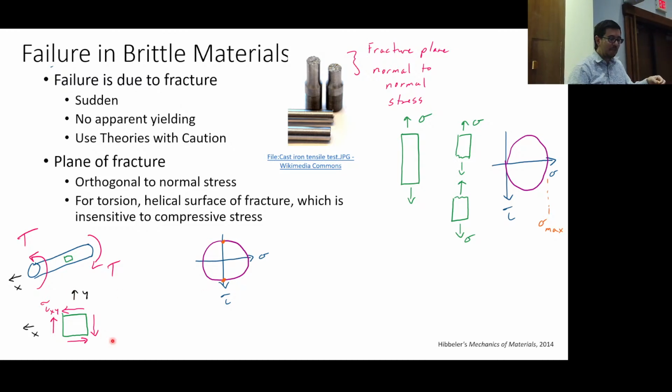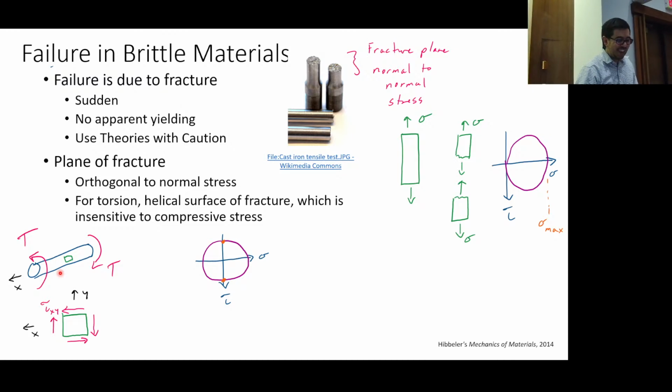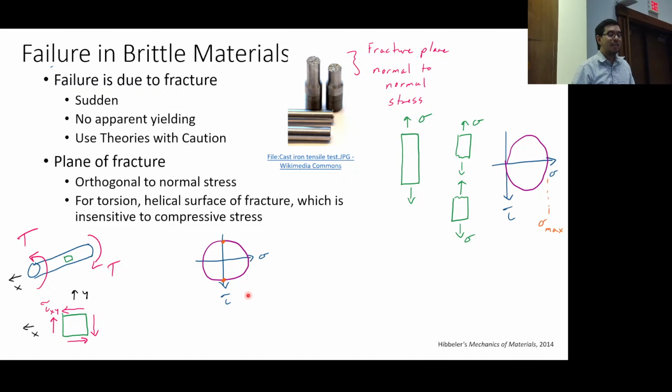What are sigma 1 and sigma 2 here? What's its magnitude? This is a coordinate system. If I'm in pure torsion, if I'm in pure shear, it's just 0. This is 0, right? Okay, so where am I on the Mohr circle? You're at the center. Okay, so that's where the center of the Mohr circle is, at 0, right?